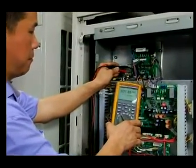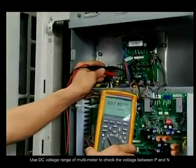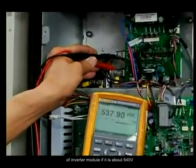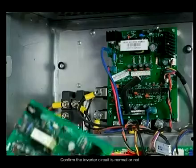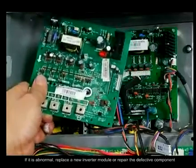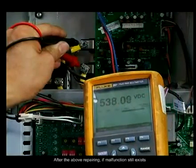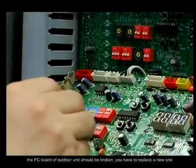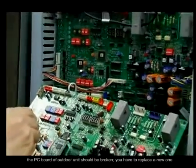Step 2. Use the DC voltage range of the multimeter to check if the voltage between P and N of the inverter module is about 540 volts. Confirm whether the inverter circuit is normal or not. If it is abnormal, replace the inverter module or repair the defective component. After the above repairing, if the malfunction still exists, the PC board of the outdoor unit should be broken. You have to replace a new one.